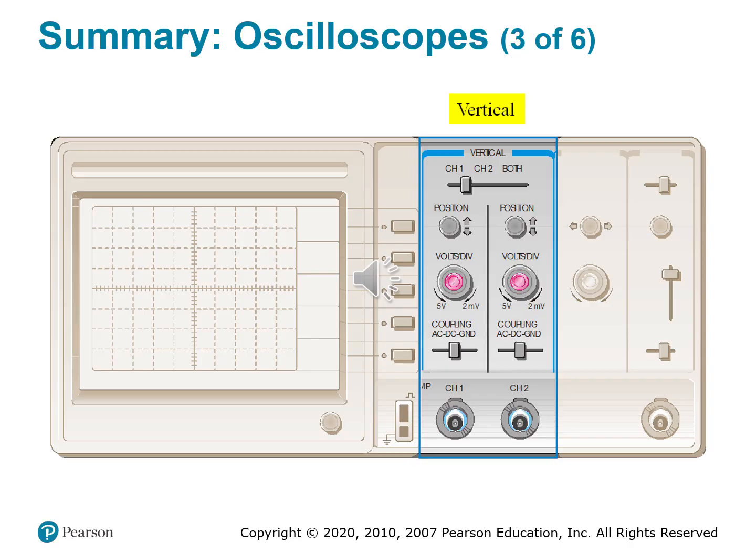Let's move on to the vertical section, where your voltage command center is. Taking a closer look at one of the most important parts of the oscilloscope, the vertical section, this is where you control and interpret amplitude, the voltage part of your waveform. Each channel, let's say 1 and 2, has its own dedicated control, so you can work with single or dual waveforms at once. Here's what each control does.